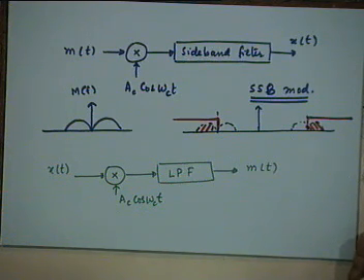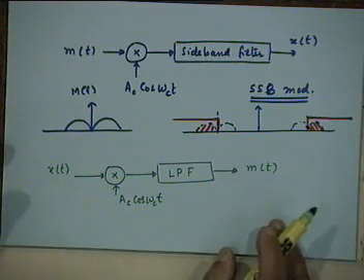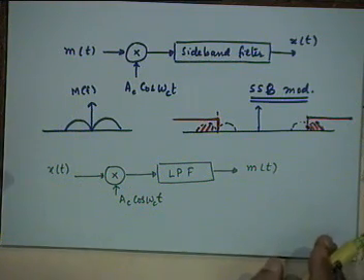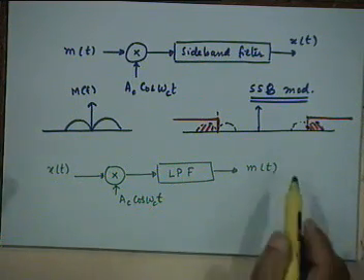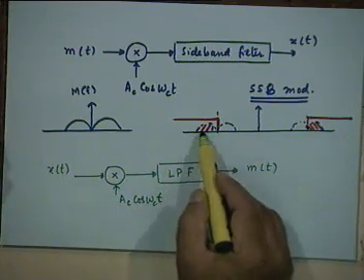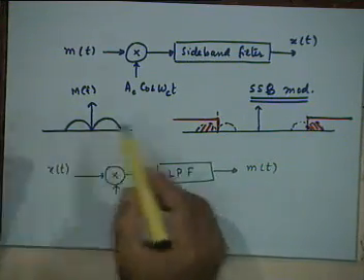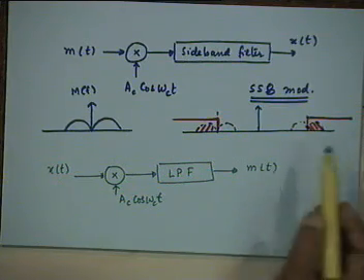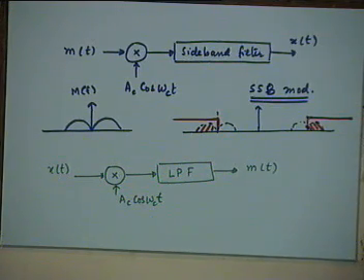Are you all with me? So the demodulator remains exactly the same that we had for DSBSC. Just apply the frequency translation theorem onto this spectrum, and you can see that your baseband spectrum comes back, along with a component around 2fc, which will of course go.